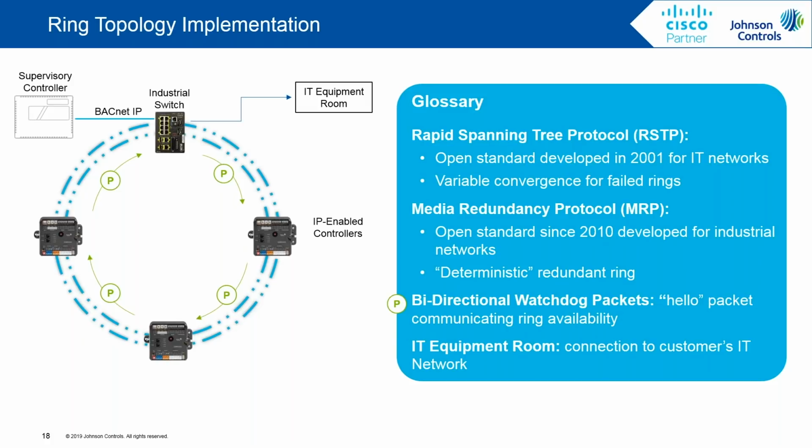It employs a method around variable convergence time. So whenever there's a break or a new member of the ring, there's a calculation that goes on. And the calculation is based on a host of variables, including items like MAC address, operating system, and some also variables which are configured in the operating system.